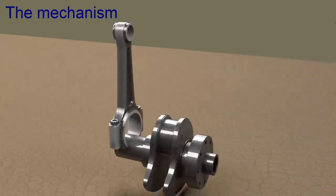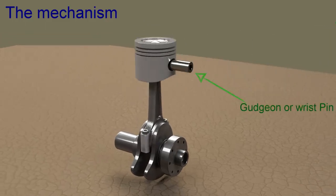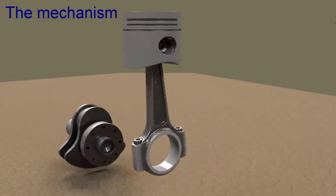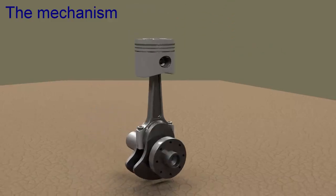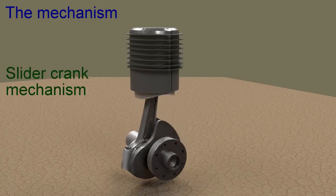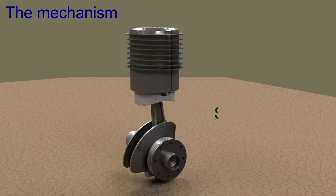The big end of the connecting rod connects to the crank and can freely rotate on the crank. The smaller end of the connecting rod is connected to the piston using a gudgeon pin, and the connecting rod can swivel around the gudgeon pin. The piston is placed inside the cylinder so that it can have only sliding motion in one direction. The resulting mechanism is known as the slider crank mechanism. It converts linear motion of the slider into rotary motion of the crank.